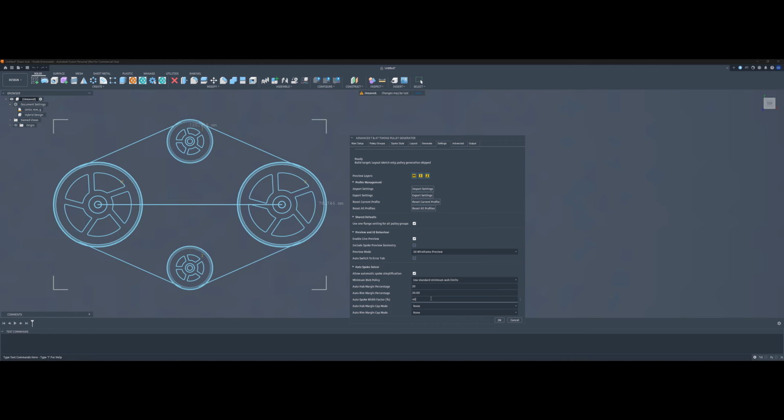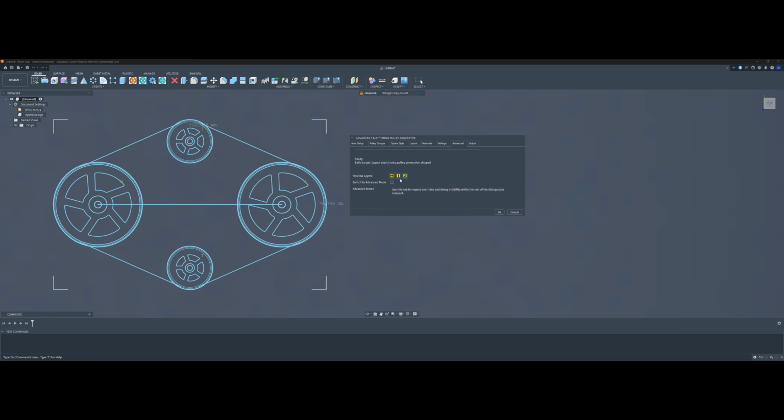The Advanced tab is mainly used for pulley tolerances. It is shown by selecting Advanced mode from Main Setup or by switching to the Advanced controls directly. The tolerance engine allows clearance and profile offsets to be applied to the pulley groups. This is useful when adjusting the pulley fit for real belts, 3D printing, material behavior, or manufacturing process.